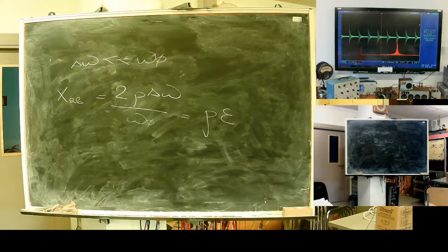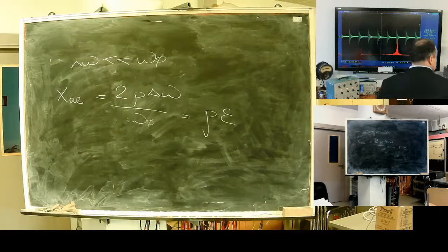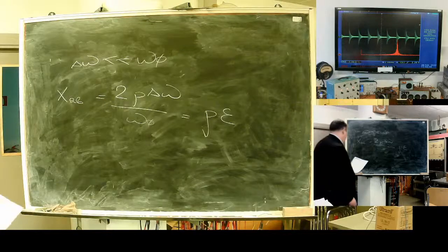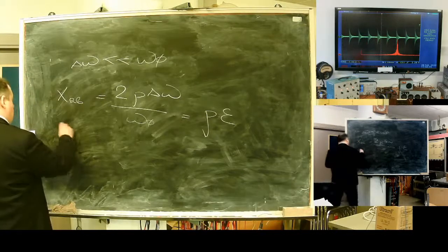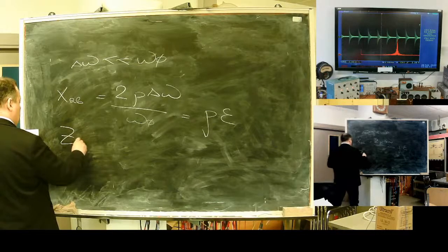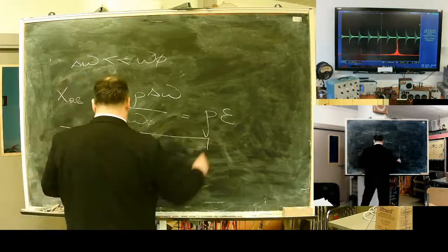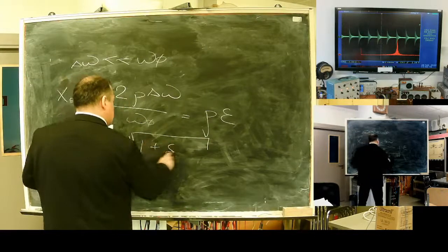Imaginary part of the input impedance is approximately characteristic or wave, some call it wave resistance, multiplied by relative frequency shift. Full absolute value of input impedance can be approximated as square root of 1 plus xi squared.